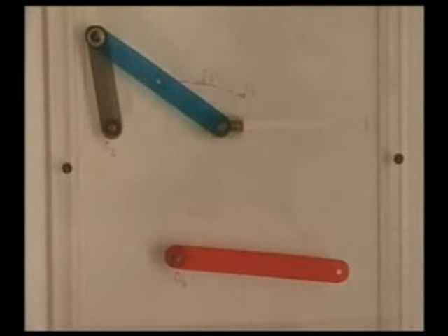Here what we are saying is that it is not only a three position synthesis for a coupler curve which is approximately a straight line, we also want to coordinate it with the input movement. That means that as the coupler point goes from first position to second position, the crank must rotate by a specified amount. Similarly, as the coupler point goes from the second to third position, we want the crank to rotate by again a specified amount. This approximate straight line coupler curve generation coordinated with the input movement can be solved in two stages, which will be explained now.